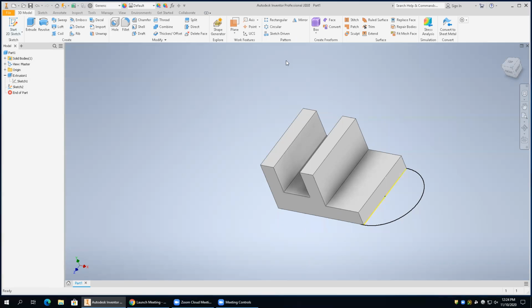The circle's diameter is set right to the edge. So if you lock it from the midpoint of that face over to the edge point of the face, the diameter is fixed. It's 2.5. So that's the extruded edge. Okay. So even if you put a dimension on there, the whole edge, it's what they call over constraint. Everybody else doing all right?